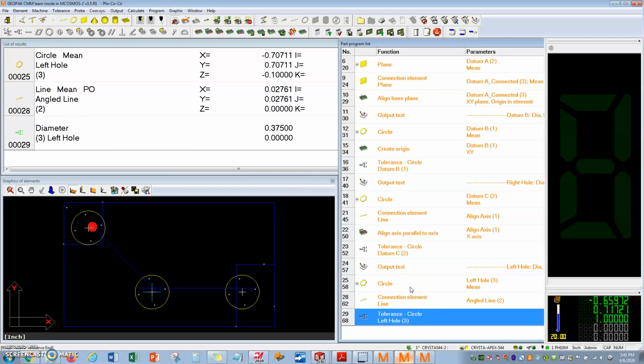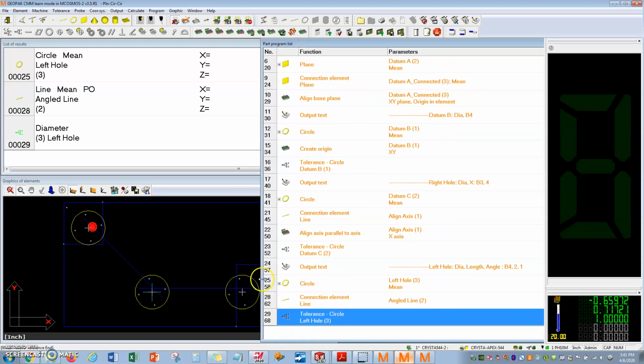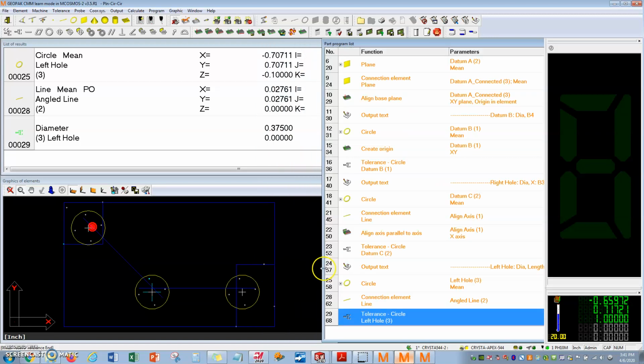And let's add that back in. So it turns out I was actually missing one field here. You actually have to create a distance for this length. It does not allow you to do that as just a line. So we have to actively come in here and create a distance.